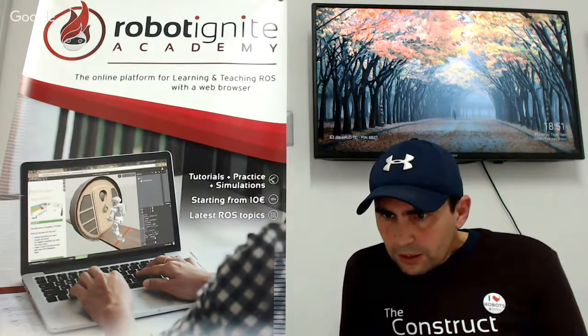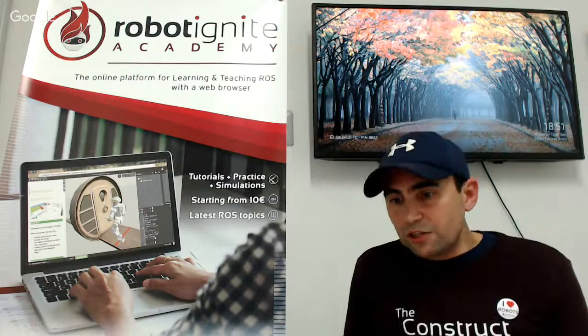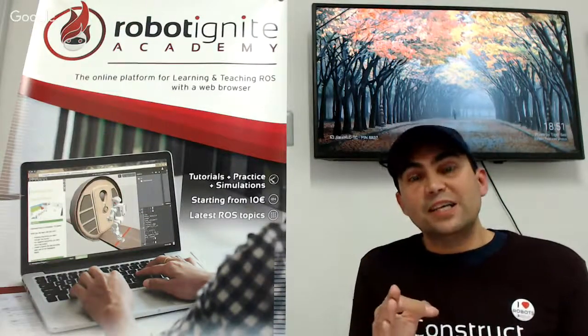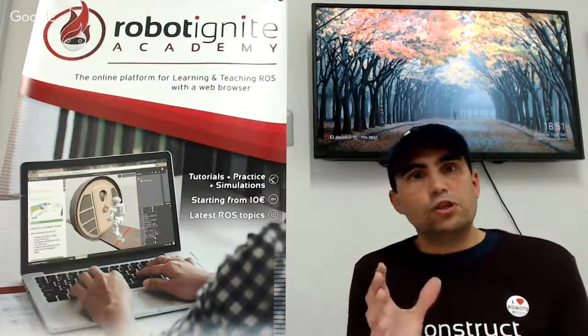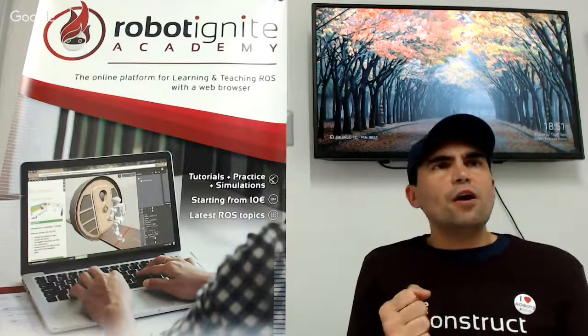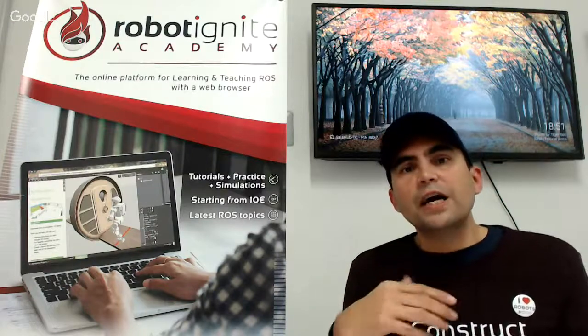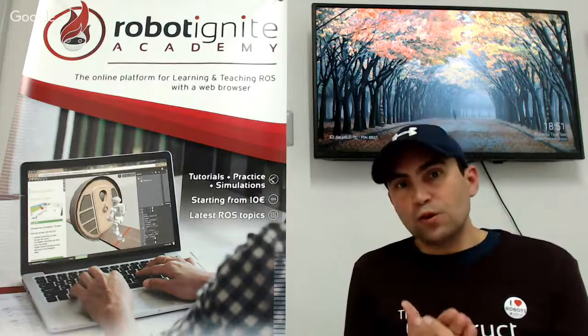What else? It's a sonar sensor. Okay, Epson Warco is talking about the HC-SR04, a sonar sensor, mostly used with Arduino. Yes, there is a sonar sensor that exists in Gazebo. It's a sonar plugin, so you just go there, take it and use it. And if it's not exactly like yours, because this specific sonar has some specificities, just modify it. You have the source code of this sonar sensor, so you can use it.